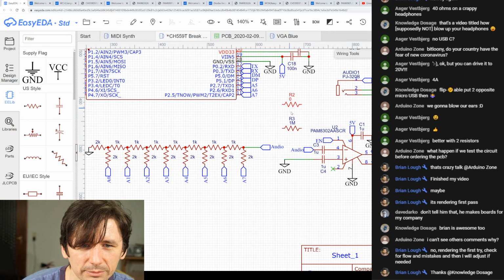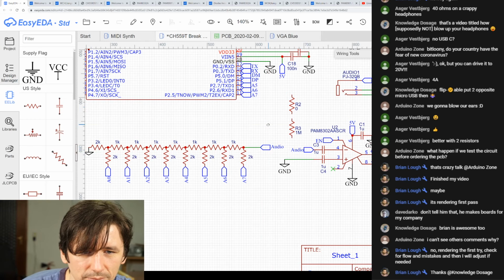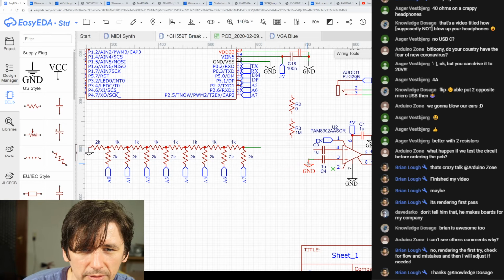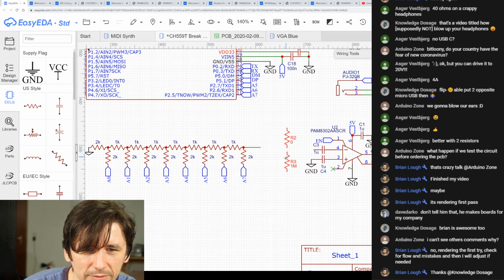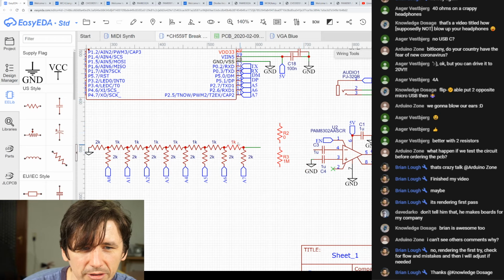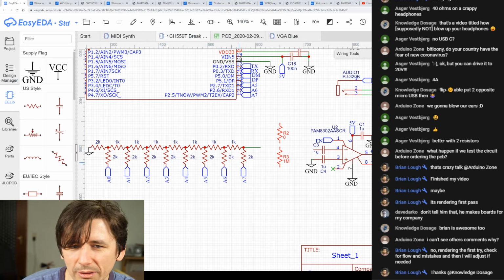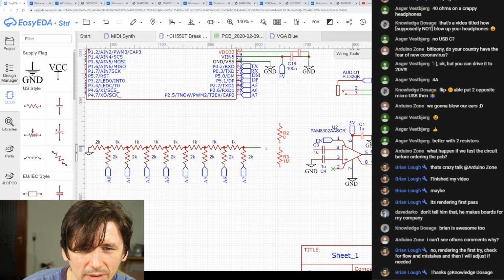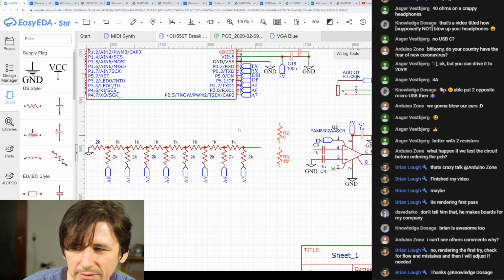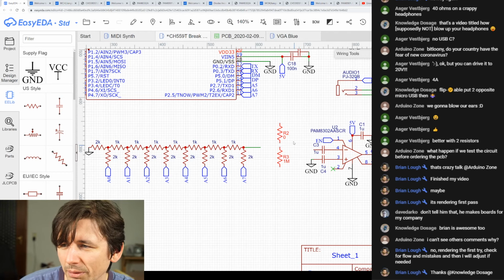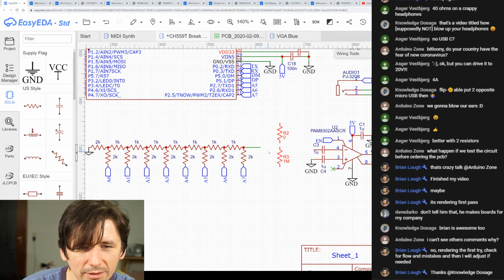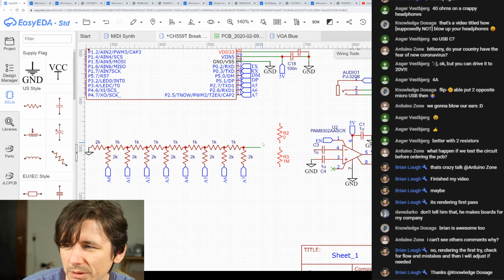Or do we divide it up front like... is it like this? So does anyone see a problem dividing the voltage here after the DAC? Because I don't know how the impedance is here. Might be problems with the DAC here. We probably would need a buffer in between. Opinions on that?